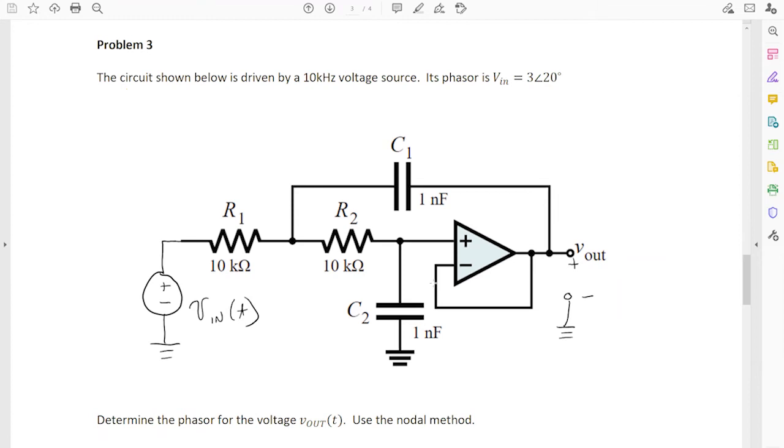Professor, for V plus and V minus, how do you know where the ground is? So, like for V minus here, is the ground the same ground for V out? Yeah, you always have to have the same ground. All circuits have to have the same 0 reference point. We could probably do a whole conversation about ground, but ground is our reference node. In any circuit, in order for current to flow, there better be a connection between everything, which means that they all have the same ground.